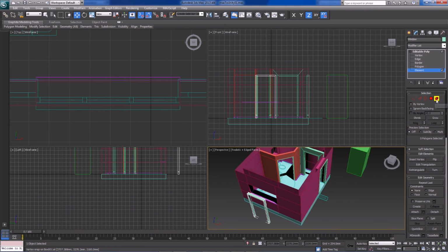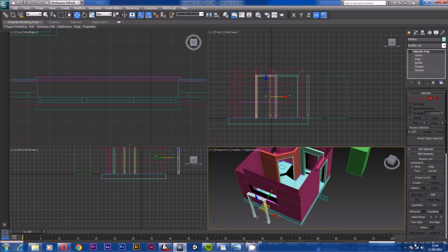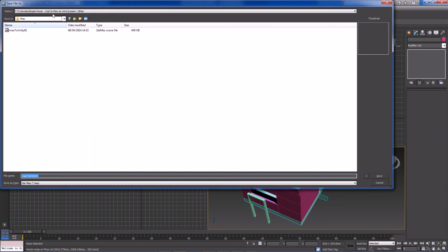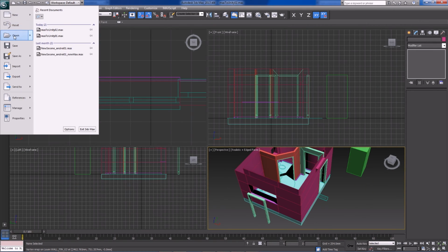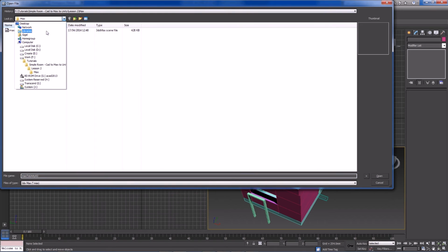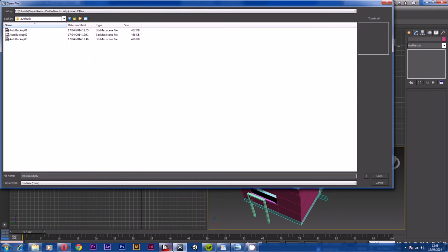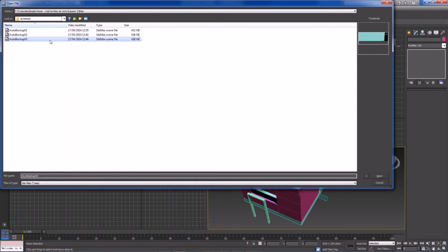So one quick way to fix this is hopefully we will have a good auto back version, so it's 12:48 right now. Quickly save this as, and this will be in lesson 2, max 2, and save it up. Let's check out if we have an auto back with the door in. So if we go to my libraries, documents, 3D Studio Max, autoback, this is usually where they're kept. Let's find the most recent file. So again, it's 12:48, so we actually have one at 12:46.